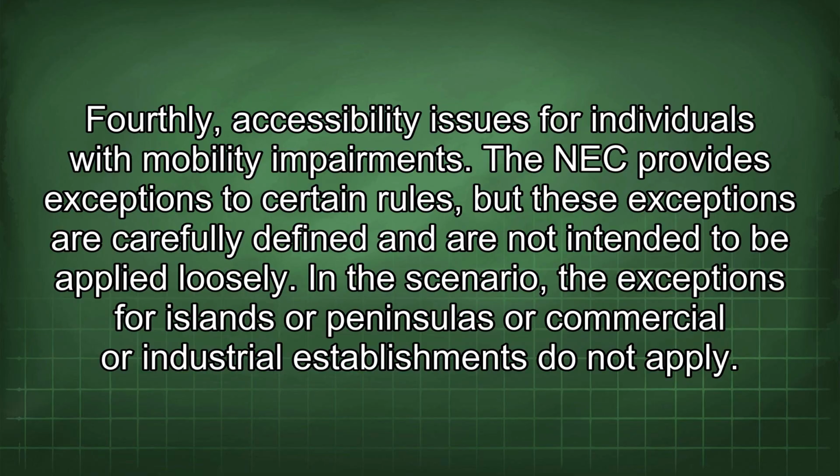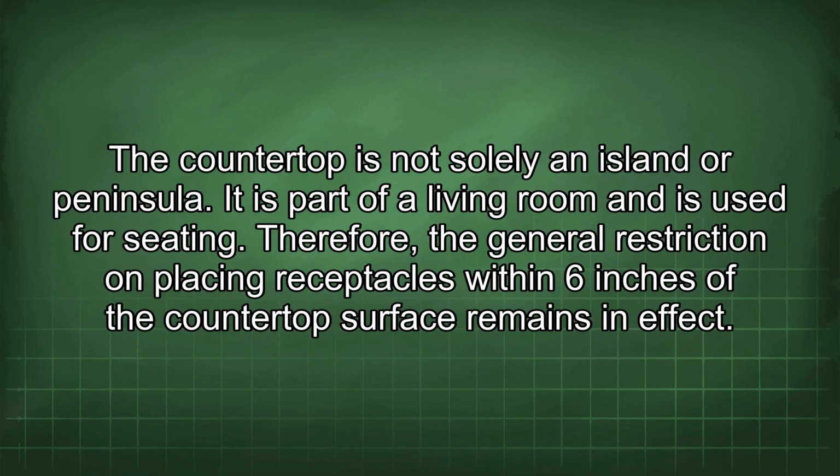The NEC provides exceptions to certain rules, but these exceptions are carefully defined and are not intended to be applied loosely. In the scenario, the exceptions for islands or peninsulas or commercial or industrial establishments do not apply. The countertop is not solely an island or peninsula. It is part of a living room and is used for seating. Therefore, the general restriction on placing receptacles within 6 inches of the countertop surface remains in effect.